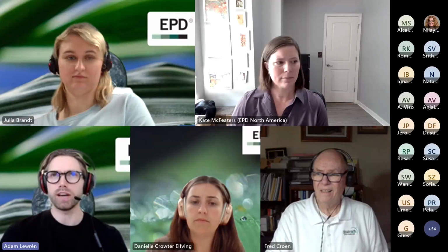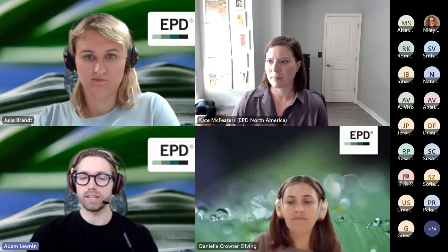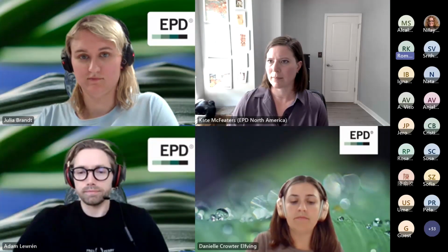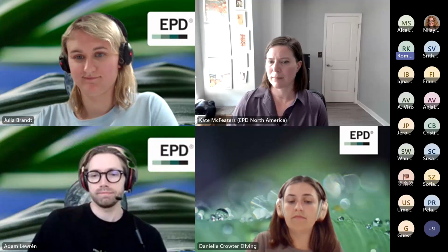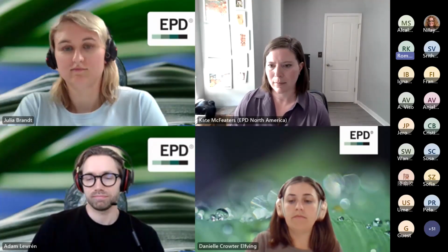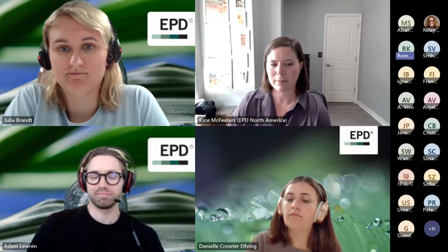In general, I don't know what product you're doing this for, but for EN 15804, the standard for construction products, there is a rule that generic data can only be 10 years old and specific data 5 years old. So there are also those kinds of requirements you have to look for in case the LCA is a little bit older. Yes, I see. Okay, then we will check, but we would have to update some things, but we can still use part of it. Okay. Yes. Thank you.